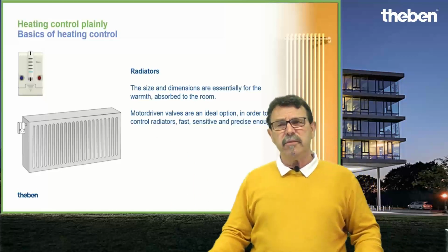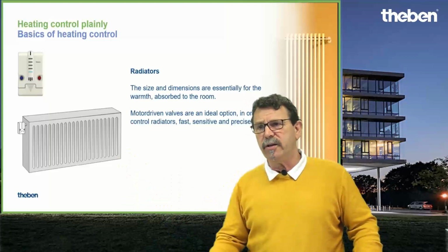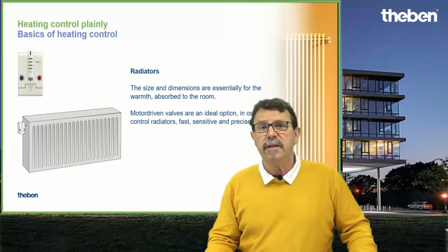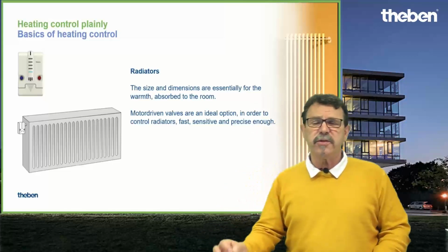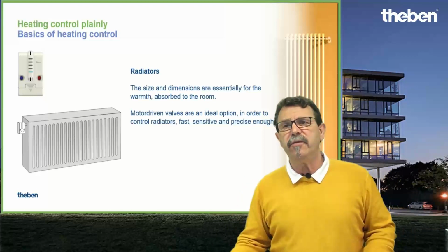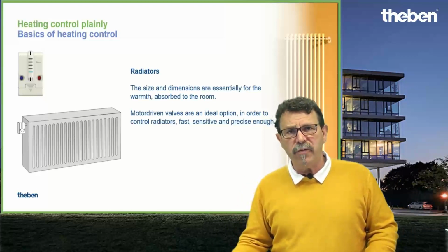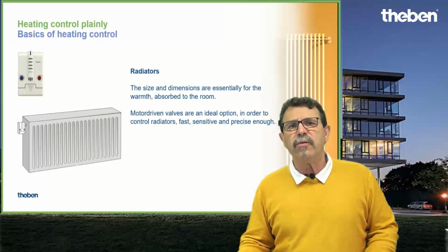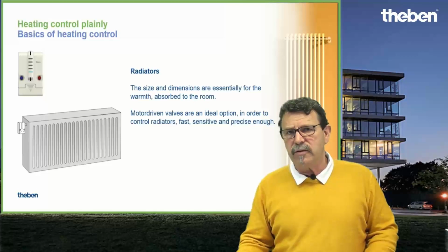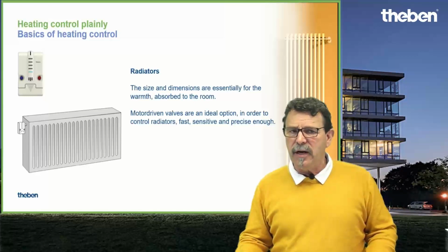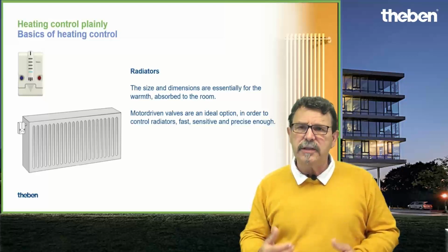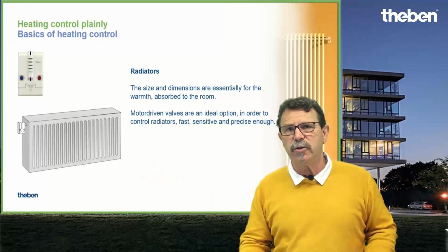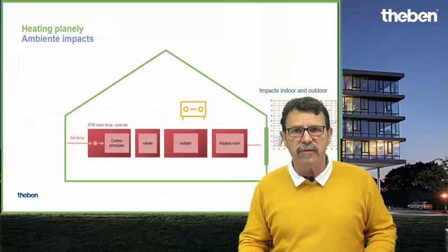Highly recommended if you control radiators like here, so there, KOPs control, for instance, a motor-driven valve is absolutely accurate and precise to control the heating value and to control the heating perfectly and absolutely precise. Terminal valves we recommend for the warm water underfloor heatings, because warm water underfloor heatings are from their control characteristic rather slow in comparison to these radiators, which we do have here on the left-hand side.